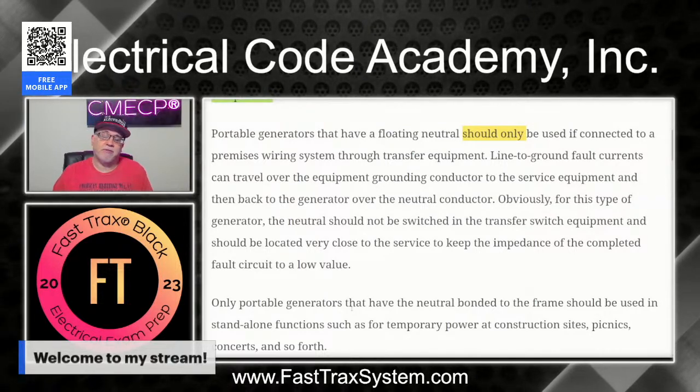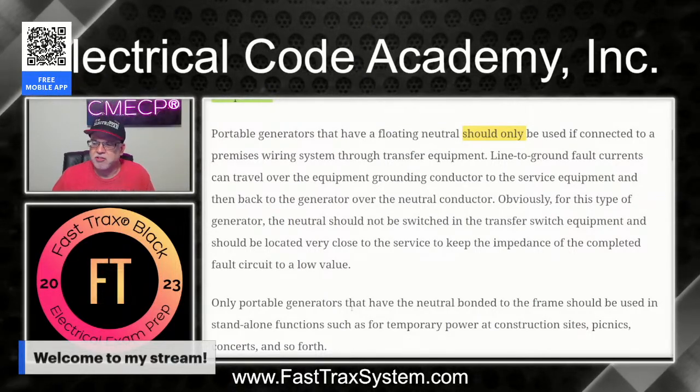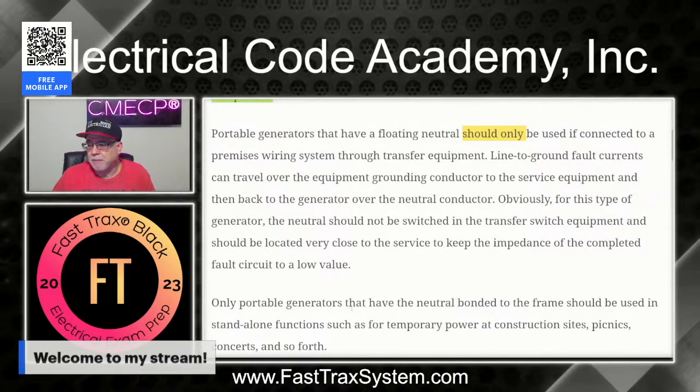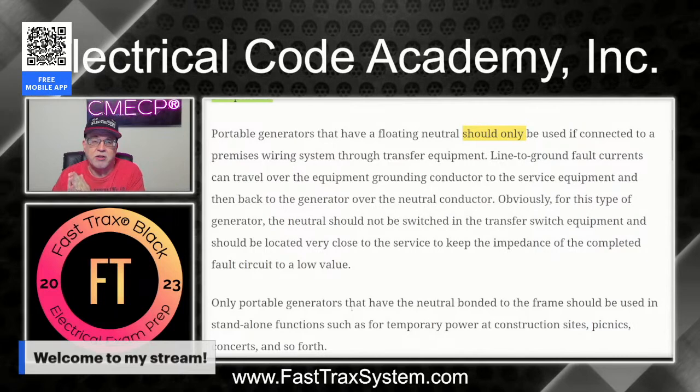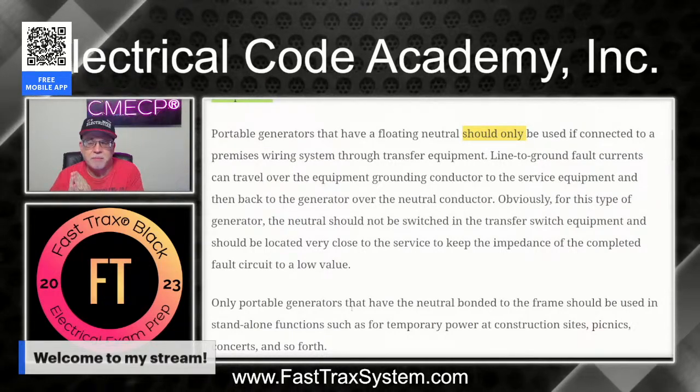And I would also say for homeowners, the people that want to buy just a portable generator to try to do backup power for their house, be very careful, because a generator with a bonded neutral is a separately derived system, right?